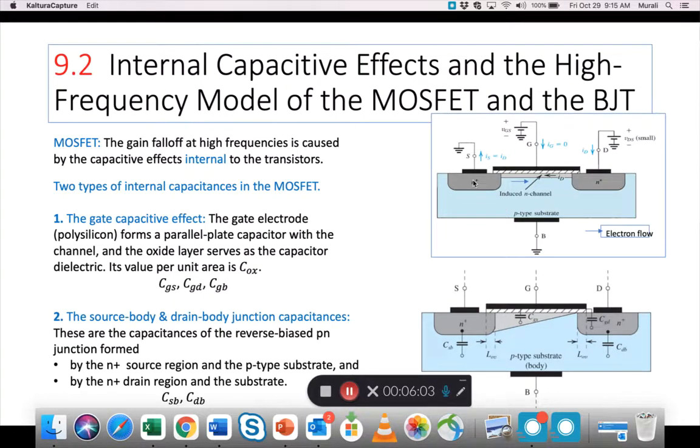There is an N-type well for source and an N-type well for drain. And the gate is in the middle and a thin channel is created, right, when you apply a voltage. Actually, that channel looks like this, not so much as the voltage goes higher, and then it's pinched off at this end. But anyway, this basic construction, and then there's this insulation material, the silicon dioxide, that exists between the gate electrode.